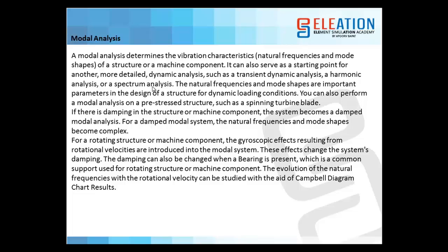This is because if there is a mode shape because of vibration, and if the loading is applied on that particular mode shape or deformed shape, then that component is definitely going to fail. So first we have to find out the different mode shapes of that component and see that the loading should not come in the same direction where the deformation is taking place. You can also perform a modal analysis on a pre-stressed structure such as spinning turbine blades.